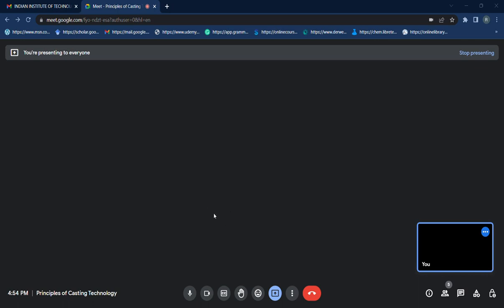So you can see from here the riser will feed 2T distance, and from your edge it will be fed by 2.5 T. Okay, then if in your problem it is given that the feeding distance in steel plates, if there is a provision of chills given, okay, so by using the chills, the maximum distance the riser can feed increases to 4.5 T plus 2 inch, in the left part and right part.